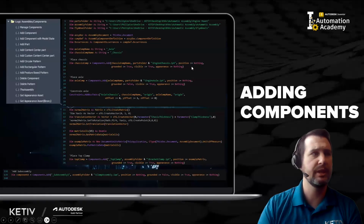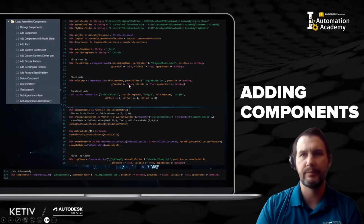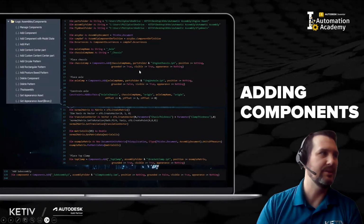We're going to position it, and in this case, we don't care where it goes. We want it to go on the origin, so we'll put in nothing. And ground it. In other cases, we won't ground it. That's important to remember if you're copy pasting code, to check whether you have grounded set as true, because later when we try to constrain things, if it's grounded, that's not going to work. And then, of course, setting it visible and different things like that.